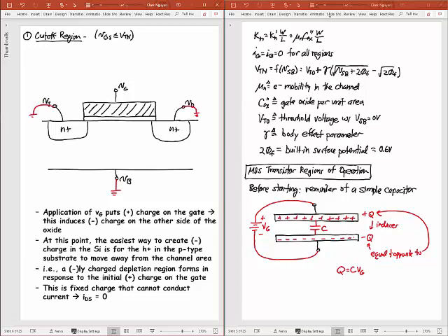So I'll ground that, but I won't ground my gate voltage. Actually, I will. It's like I'm putting 0 volts on it, but I'm going to allow for voltages less than VTN. Right? 0 is less than VTN, where VTN, like I said, is about 0.7 volts. It could be 0.7 to 1.5 volts. But here, I'm going to allow for that by saying that I'm putting on this node a voltage VG. So I put VG on that node right there.